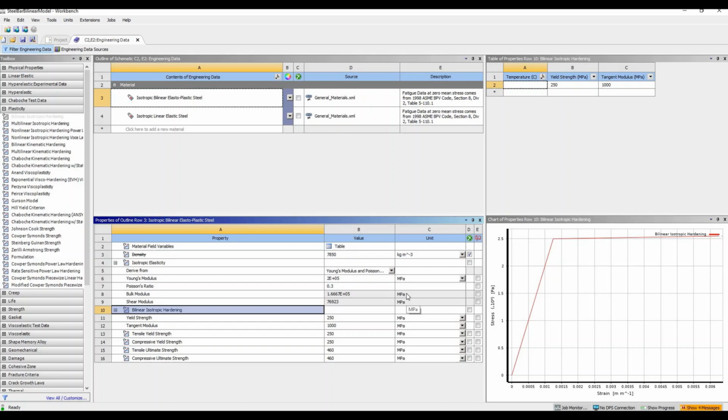and it's going to be constant in the sense that the plastic modulus will be constant, so it's not going to be a plastic modulus that will change with loads or stresses. So it's a very simplistic plastic model, but it's much more powerful than the linear elastic isotropic model that we have studied before.